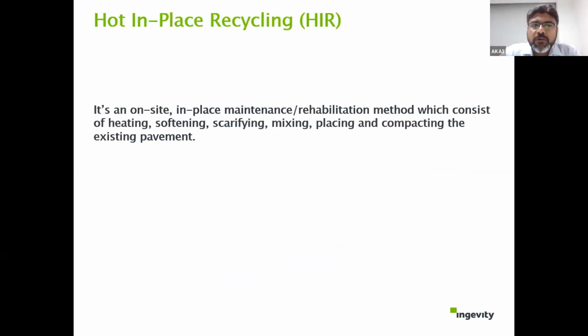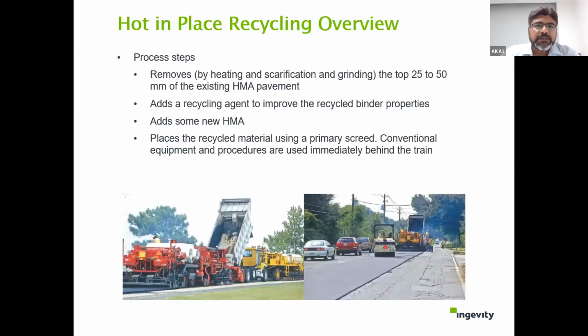So hot recycling, we all know what it is. It's an on-site, in-place maintenance and rehabilitation method consisting of heating, softening, scarifying, and doing the work on-site without taking anything to the plant. The typical first step is we remove it. We add a recycling agent, sometimes yes, sometimes no. Why we add the recycling agent and what it does, we'll see in detail. I'll also try to show some of the projects that we have done across the world. We also add the hot mix part, and how much recycling we add is the total impact that we are going to see here.